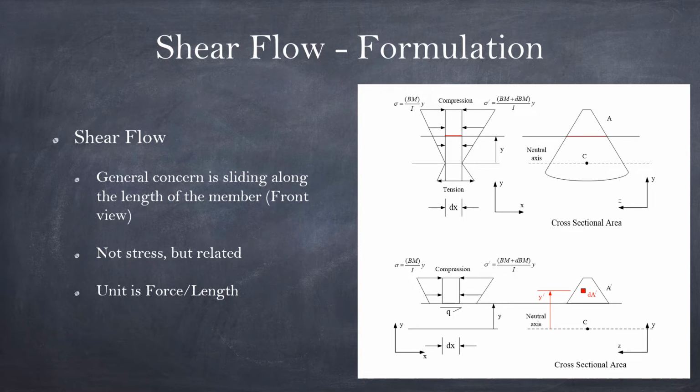On the right-hand side we still have to find A prime, and of course we have to designate the point where we are looking at the stress, sigma and sigma prime, so that we know how to set up the integration equation for the force in the x direction. Again, it is restricted the same way we restrict the shear stress, because we take the shear force, or the transverse shear stress, out of the picture.